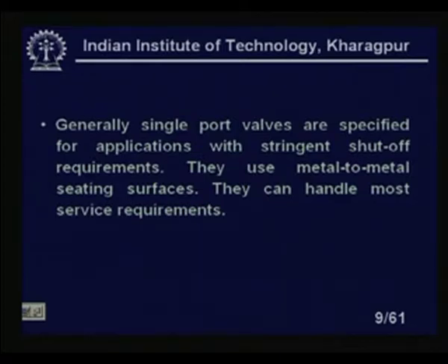Generally, single port valves are specified for applications with stringent shut off requirements, where the shut off is very tight. So, I need this type of valve. You may ask, why should I use a butterfly valve then? As I told you, the response time of the butterfly valve is very short. That means it takes very quick action, whereas the sliding stem single port valve takes more time. But if you need a very tight shut off, I have to use a single port valve.